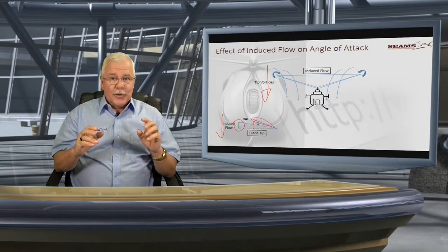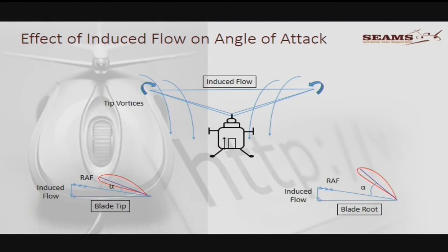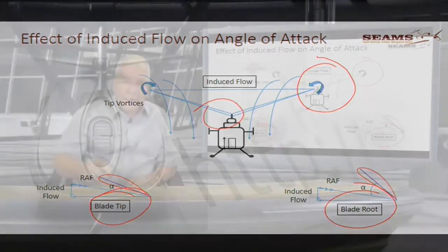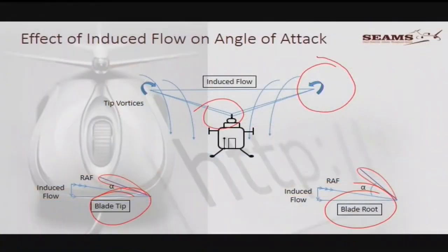All right. So now you can look and you can see on the same picture, if we look at the root blades here, they're going faster. The blade angle might be higher. This is the root, sorry, this was the tip. So the inside of the blade here, the root side, you can see the angle is already higher, and that is obviously because of washout and design and so on. I'm not going to go into that now. But the net effect stays the same.